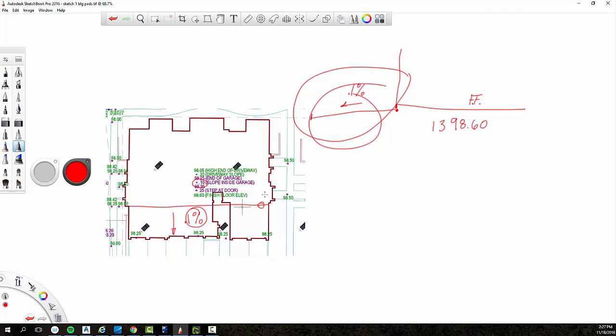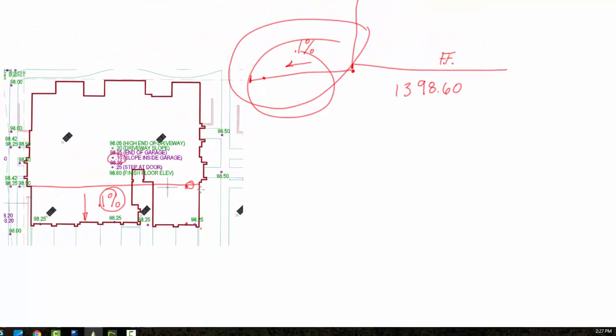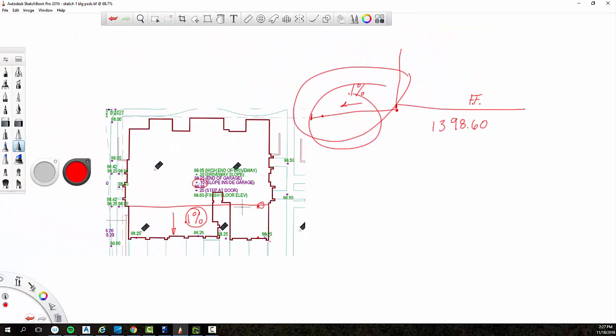And what we'll do is then we'll be able to run around this polyline of the garage area, and it'll pick up that slope. So for example, if this is 19 feet from here to here, then maybe the elevation is here to here, and maybe this is the 20, so then that goes out here. So this will all constantly be that 0.1% around the garage area.